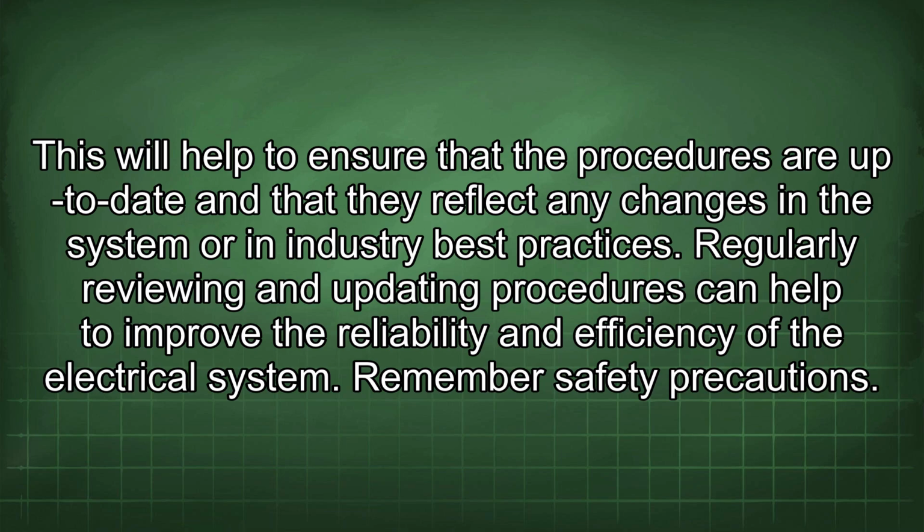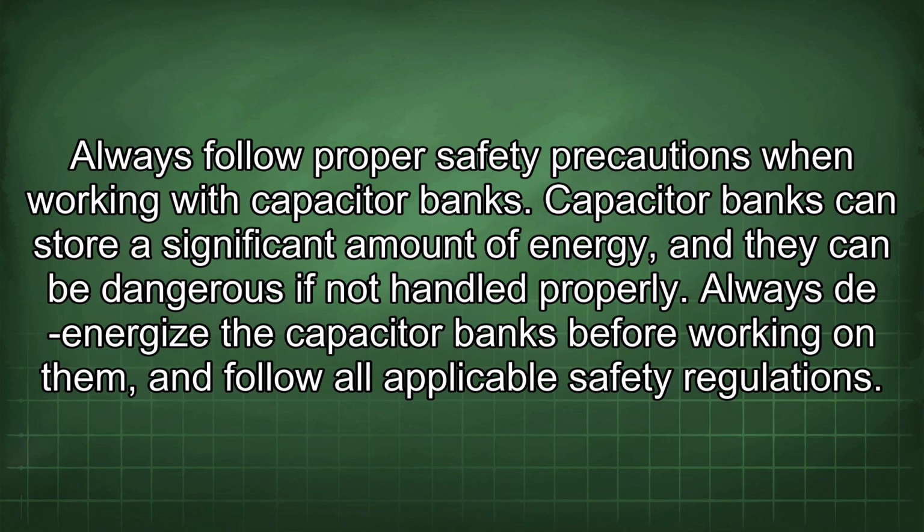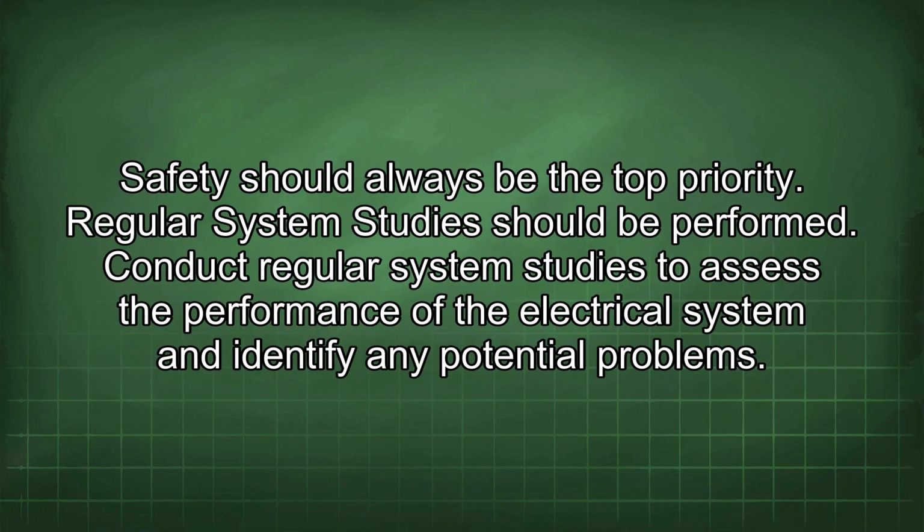Remember safety precautions. Always follow proper safety precautions when working with capacitor banks. Capacitor banks can store a significant amount of energy, and they can be dangerous if not handled properly. Always de-energize the capacitor banks before working on them, and follow all applicable safety regulations. Safety should always be the top priority.